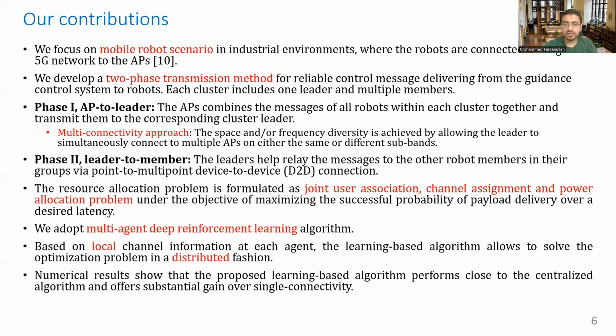And we divide the communication into two phases. In phase one, the APs combine the control messages of all the robots within the cluster and transmit them to the corresponding cluster leader. And moreover, the cluster leaders are able to utilize multi-connectivity to connect to multiple access points simultaneously to increase the reliability.